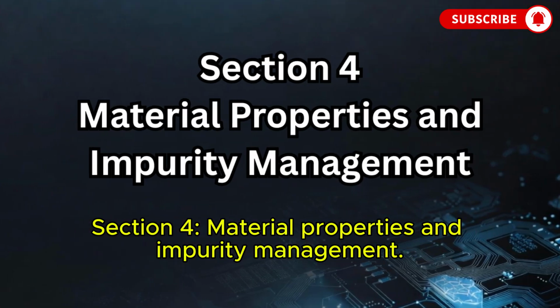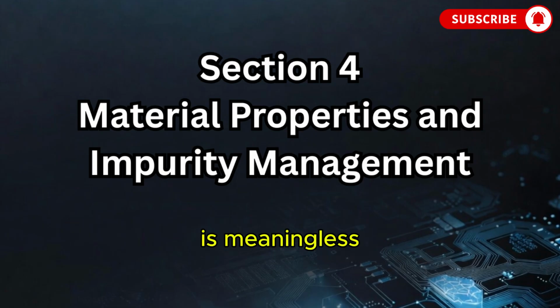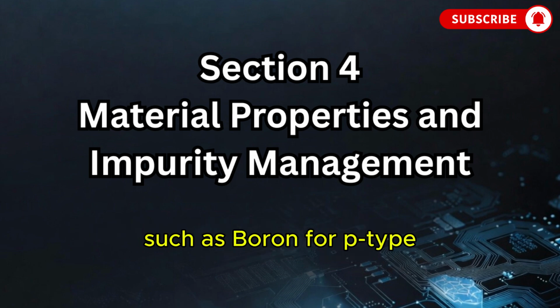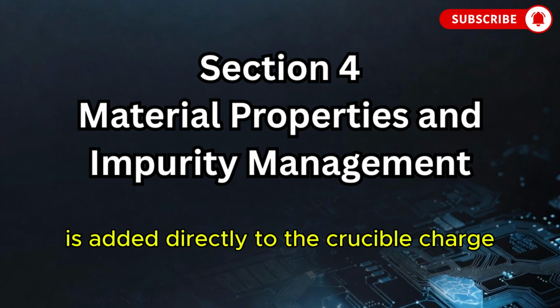Section 4. Material properties and impurity management. Controlling the geometric shape of the ingot is meaningless if we do not also control its electrical properties via dopant control. A precise mass of dopant material, such as boron for p-type or phosphorus for n-type semiconductors, is added directly to the crucible charge.